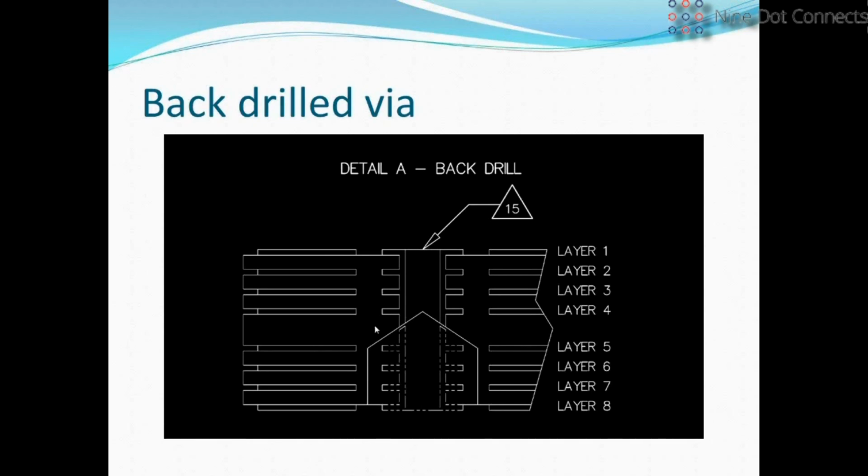They often will do this for hot pad removal when you've got a solid sheet of copper that you're going to use for sinking heat out of an RF design. Some of these amplifiers will sink several watts of dissipation, forcing you to have intimate contact with the back of the board.